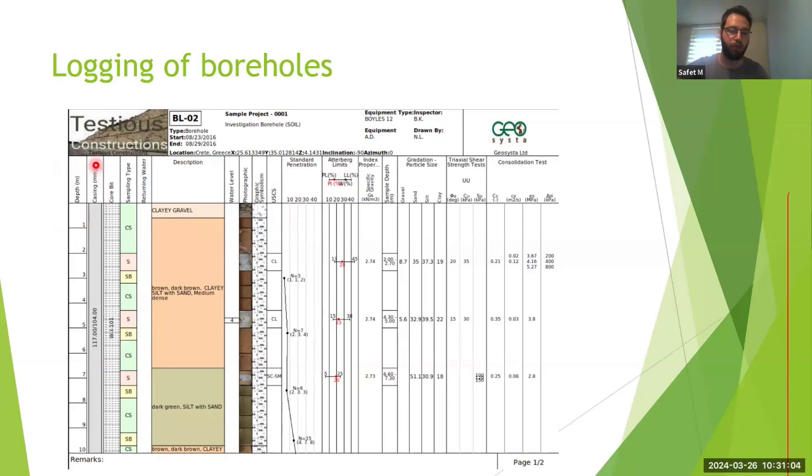The core bit that you use, the sampling type, returning water or losing the water in some cases, and the geological description would just cover some basic stuff you saw there. If there's a water level there, say 5-meter depth, you're also going to see the dates of the water levels, because it will change over time.